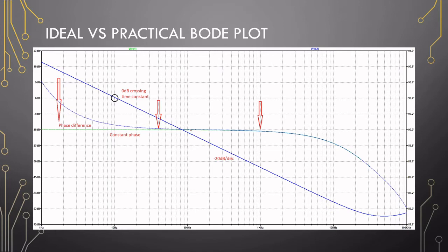So if the phase doesn't bother you, it doesn't matter, but if the phase does bother you, then the integration area will only be between these 2 points where it's kind of a perfect integrator. Then you need to design for your frequency to be between these 2 points.